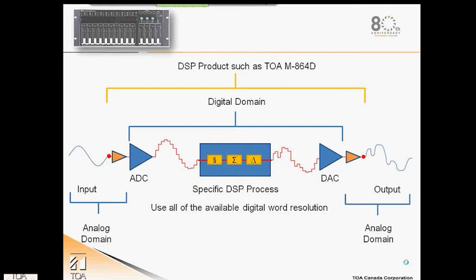So what does this process look like in a typical audio product? On the left we see the analog signal entering the ADC. The conversion is then applied as described above. Once digitized, specific processes can now be affected by the microprocessor or by manual control by the operator. After processing, the results are then converted back to the analog domain for further processing by the amplifiers and then delivery to the speakers.